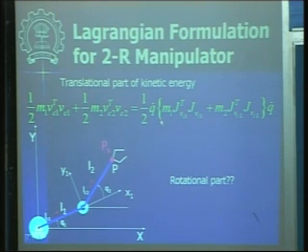So in the general fashion, you can write this velocity as Jacobian transpose multiplied by Jacobian into mass, and then this is m2 again multiplied with the Jacobian transpose and Jacobian, and then this matrix will be the part of a D matrix contributed by the translational energy.